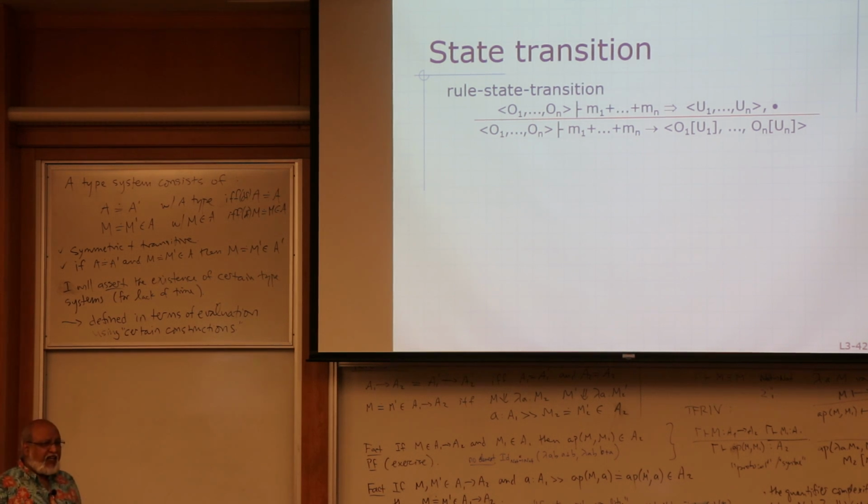This is exactly how BSV hardware behaves. A rule may go all over. It calls this method, that method. You can call methods all over the place. But state change is all simultaneous. At the end of the clock period, all those registers will get updated. That should have been updated, which may be spread across many modules.